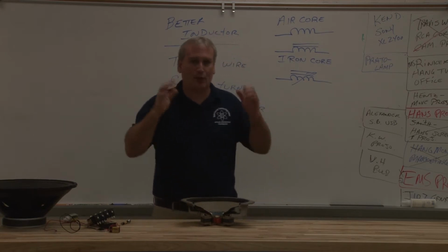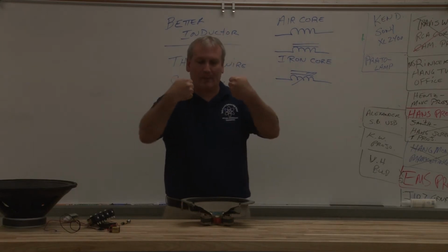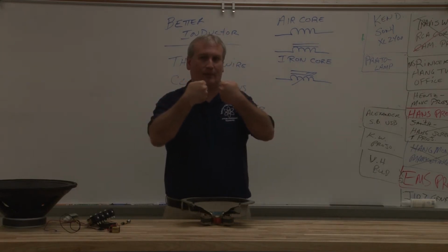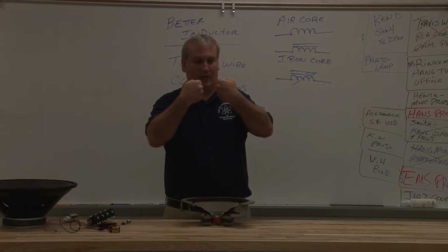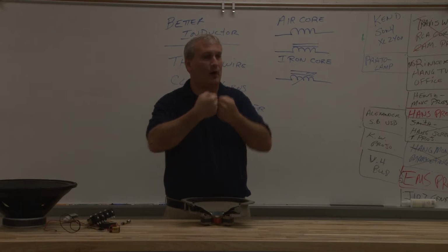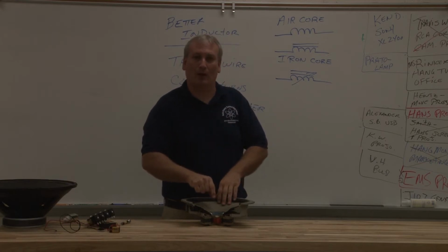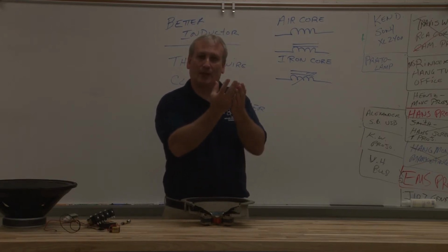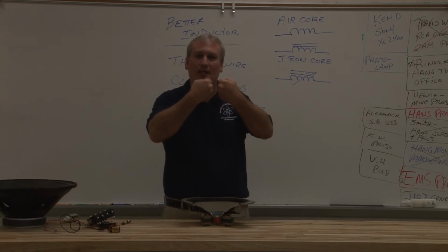Now we know if we take 2 magnets, if we start to bring the magnets to each other, what's going to happen? Seth? What's going to happen to the magnets? They're either going to repel or attract, depending on what their poles are. Well, when I have current flowing through the voice coil, I build up a magnetic field. I now have a fixed magnet. So even an electromagnet and a fixed magnet, a permanent magnet, will attract and repel.